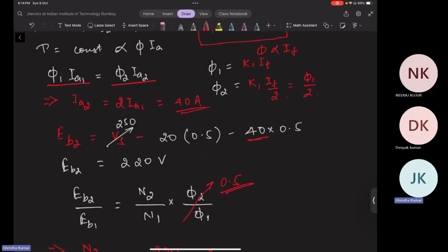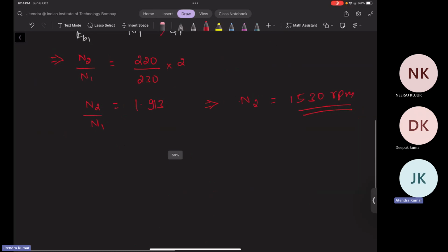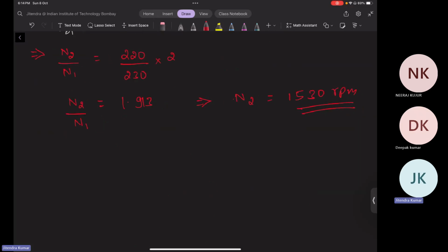Whenever we deal with a DC series motor, the field current and armature current are always coupled. Both are coupled to each other. So you cannot independently change the flux and tweak your armature currents to get the desirable torque at desirable speed, which is quite possible in a shunt machine and other machines.